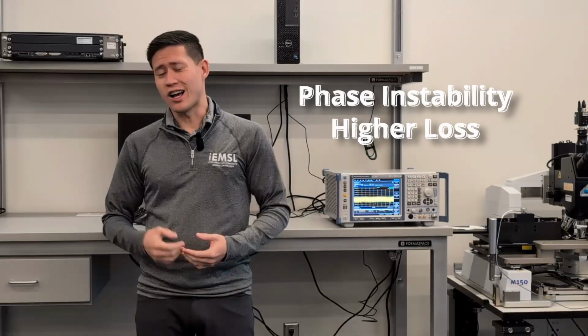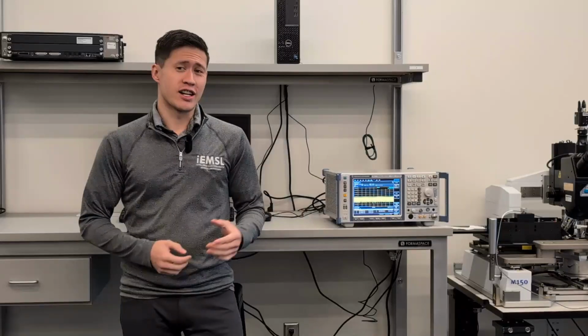So yeah, each type of coaxial connector has a maximum frequency. What that means is that if you try to use a higher frequency with that connector, your measurement will suffer from phase instability and also higher loss. In order to know the maximum frequency of a certain connector, you'll need to know what type of connector you have in the first place. And in the iEMSL, we mainly use 7 different types of connectors.